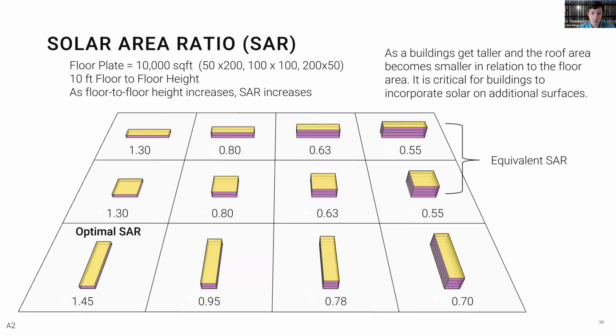Generally speaking, BIPV requires a coordinated effort in a big way. The architect needs to be involved. The general contractor needs to pull together the right trades that all understand their duties and their scope of work. Typically, glazers will integrate the technologies into their glazing systems, but then an engineering firm coordinates the design and how all of the glazing units get wired together. If a glazer deals with wiring, it's usually only on the DC side, because maybe the wiring is integrated into the glazing units themselves.